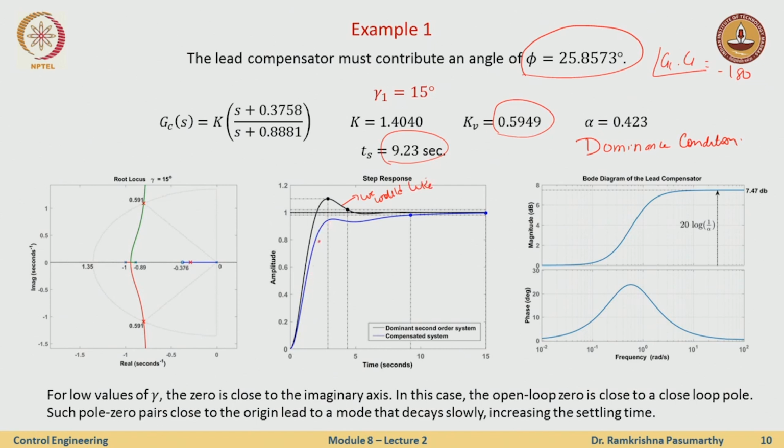Of course, it is a little strange behavior here, that there is no overshoot, but there is still a little, it goes down and then it results something like this. The MP criterion is met, but we are not really happy because that is not just the objective. Your settling time is fairly large and the errors have increased. So gamma equal to 15 is a wrong choice, even though this is satisfied. Okay. So this plus this is not the sufficient condition.